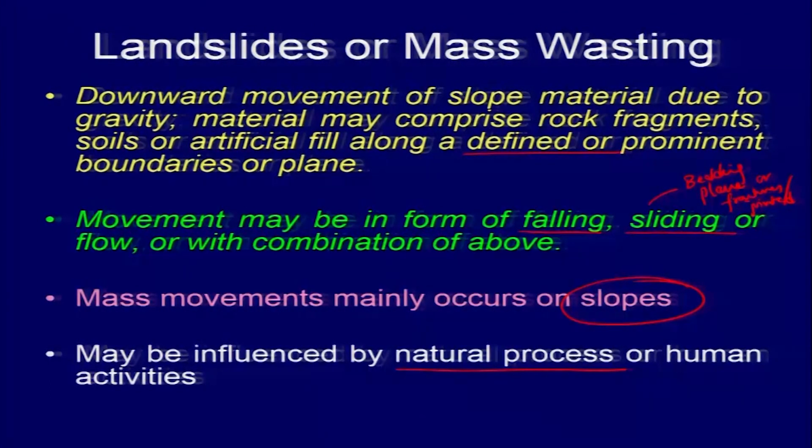If you are having a very high pouring down of rain, then you may have issues with the material sitting on the slope. If a lot of material has been poured or put on the slope, that is an overburden, then also that will trigger the landslip.